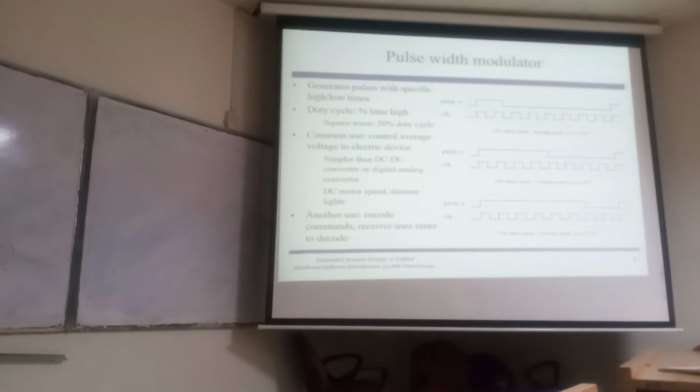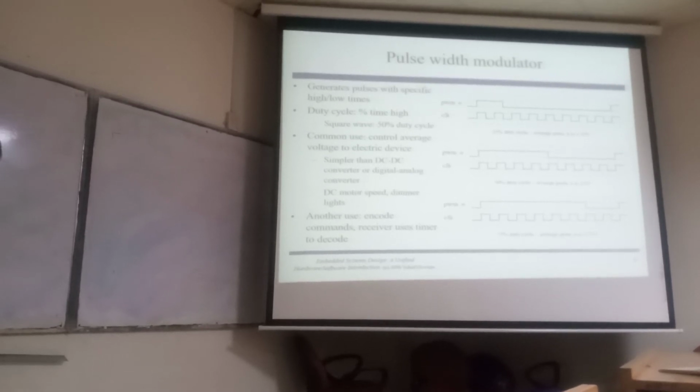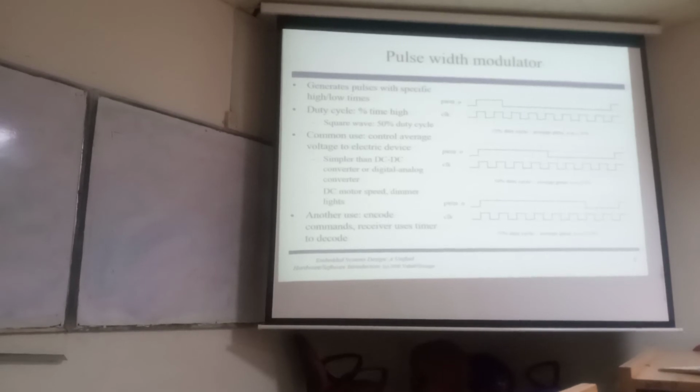The amount of time it stays on. Yes, the percentage of time a pulse is high compared to the low time. So actually, what is duty cycle? Duty cycle is equal to high time divided by high time plus low time.